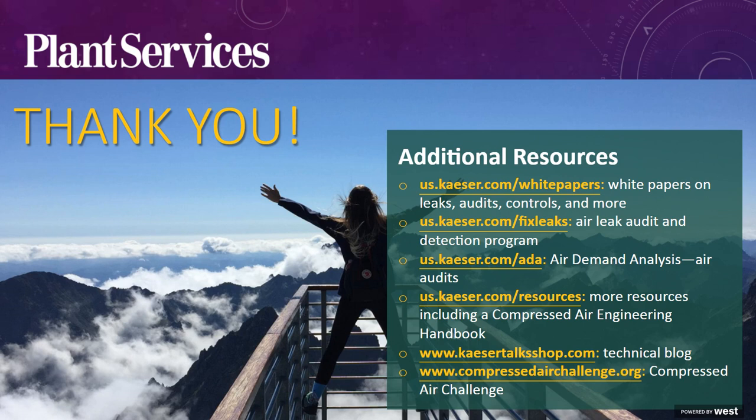Have you seen or used a new sonic air leak imager to help detect plant leaks? Yeah, that's a good question. Me personally, I have not. What we do use, the leak detection equipment that's out there, there's a lot of pieces, and it does use volume, so audible decibels. Based on where you are and how close you are to that leak, the noise level it detects, sonic, can give you an idea of what that flow is.